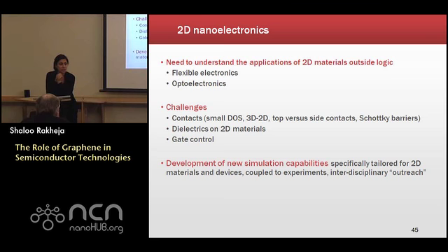But I don't know, York, I think you have worked on extraction of contact resistances and things like that. Do you think experimentalists would be able to understand that there are differences between electrons and holes? Well, we have proposed a model, and John had worked on that as well, with different contact metals. If you're using top and back gates, then you can really shift the respective curves, namely the curve that comes from the contact gated region and from the middle gated region, relative to each other, and can really disentangle those resistance contributions.